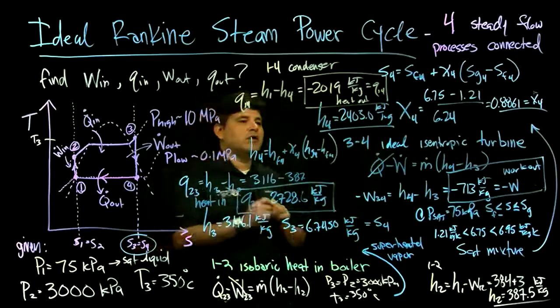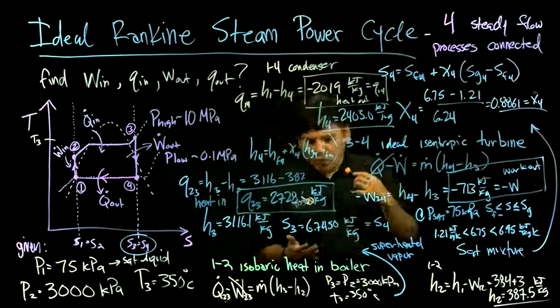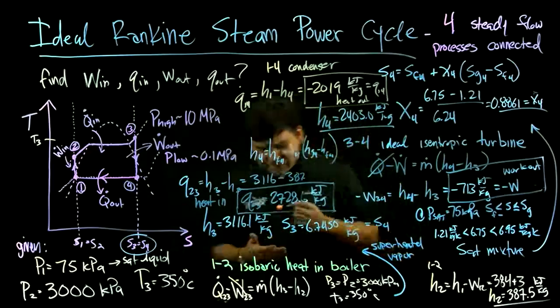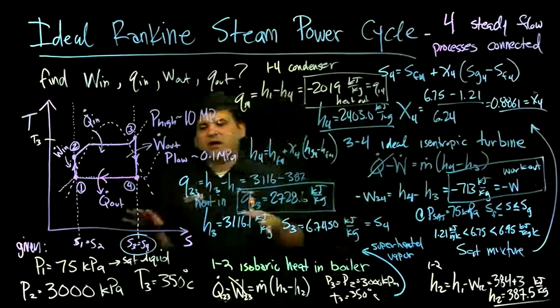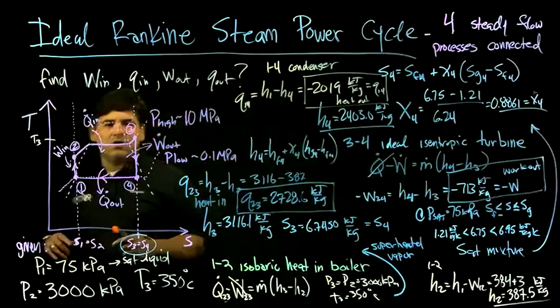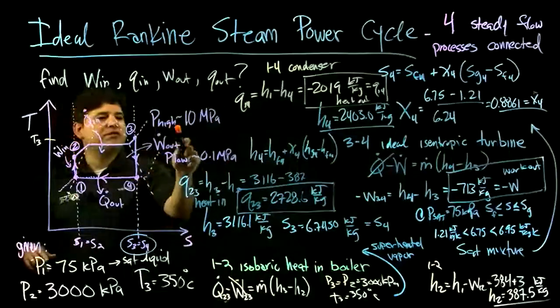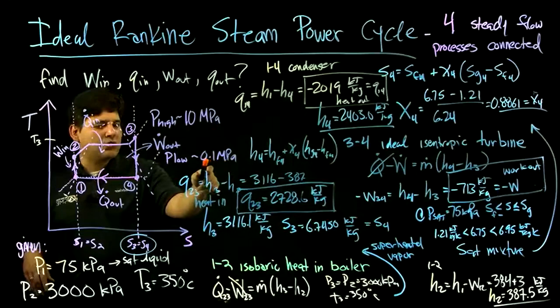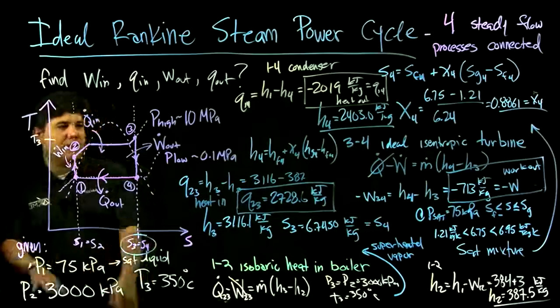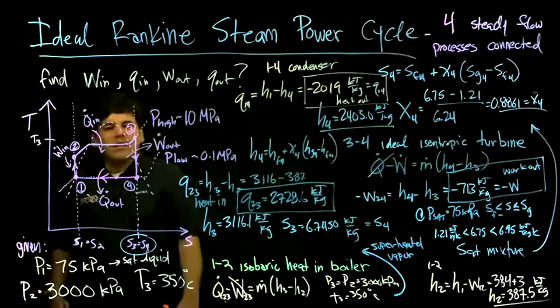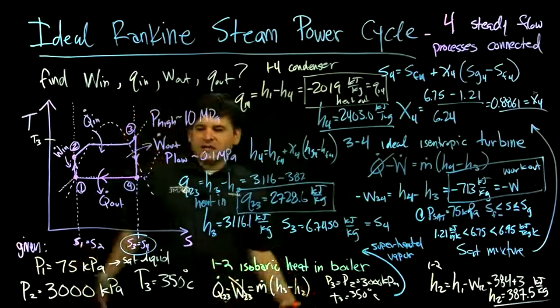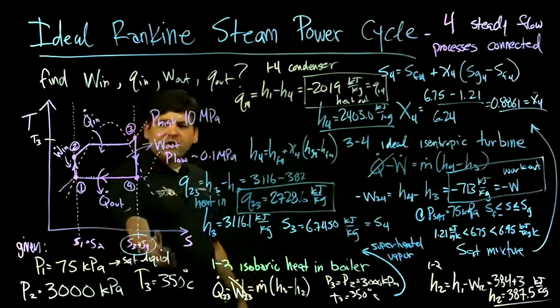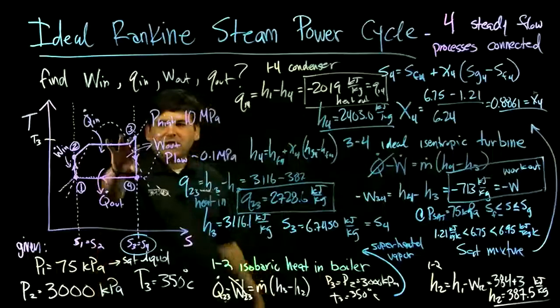So what did we learn here? Well, what we learn here is that heat engines, these are typical values. This is an ideal cycle, but as we said, these pressures are typically 1 megapascal to 0.1 megapascal. That's kind of what we had here. And for steam, that constrains the temperatures, 350 Celsius, that's on the steam table as superheated vapor.